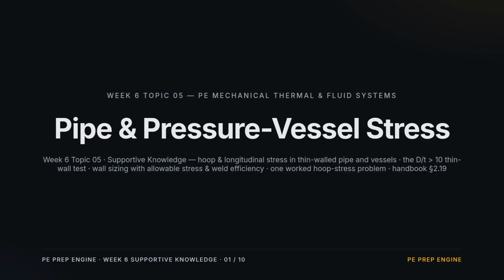Topic 5 of Week 6, Supportive Knowledge. Pipe and pressure vessel stress. Internal pressure loads a cylinder's wall in two directions at once, and the handbook gets closed forms for both when the wall is thin. We meet hoop and longitudinal stress, the 10-to-1 thin wall test, the wall sizing formula with allowable stress and weld efficiency, and finish with one clean hoop stress problem.